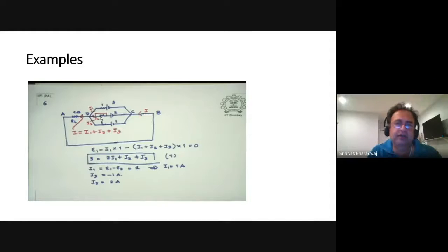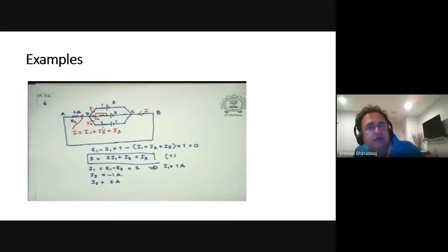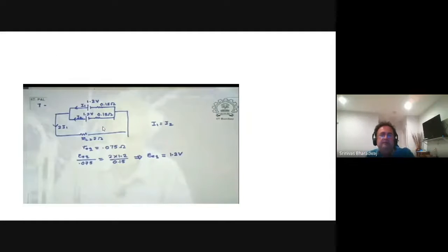So now you've got the equivalent of these two. Then I will do that one more time with the EEQ and REQ with this one, and find the resultant EEQ, and then I will solve. Then I will have an internal equivalent resistance and 1 ohm along with it, so that will produce the effective resistance. That's what you should do in solving these problems.